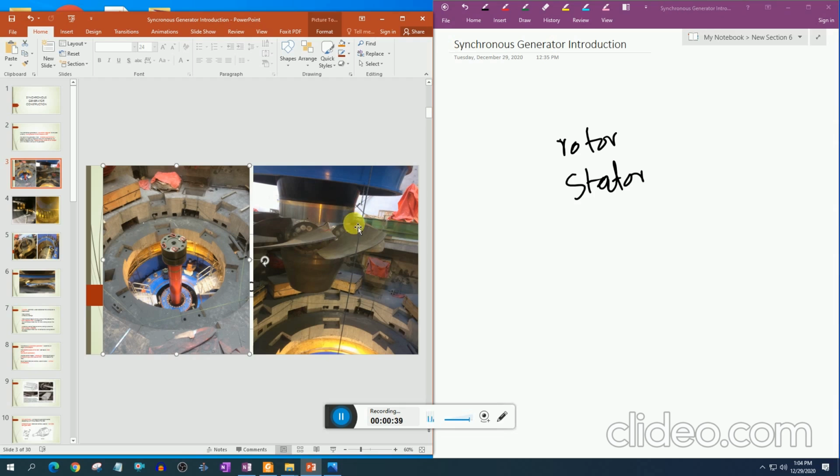Water strikes these blades. These are the runner blades, and it starts rotating, and when it starts rotating, the whole shaft starts rotating. The rotor is present at this place, and the rotor starts rotating, and the stator will be present on the outer side. The magnetic field on this rotor induces voltage in the stator winding, and it is collected at the end towards the transformer and then supplied to the 132 kV transmission lines. So now here I am showing you the shaft and the turbine.